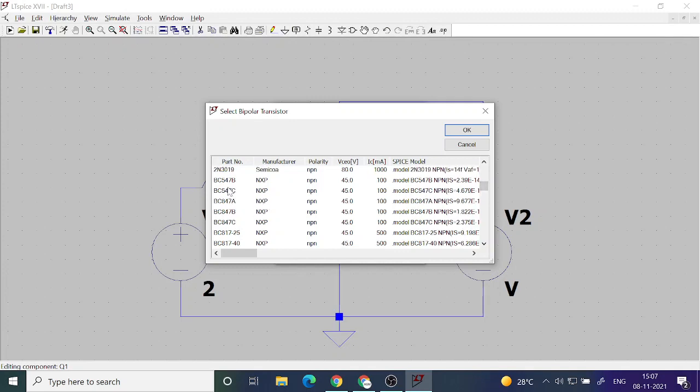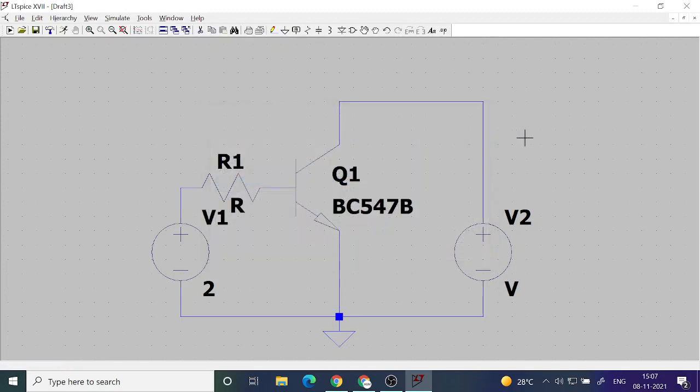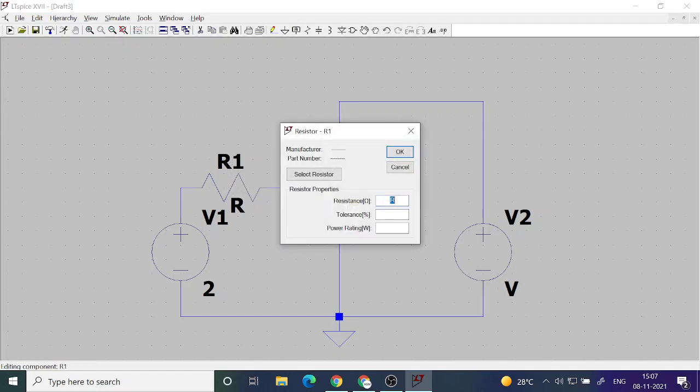So that is here, let's put that. And the purpose of this resistance is just to limit the current, so that the forward biased diode doesn't get a very large forward bias voltage. So you can put something like, say, 500 ohms.